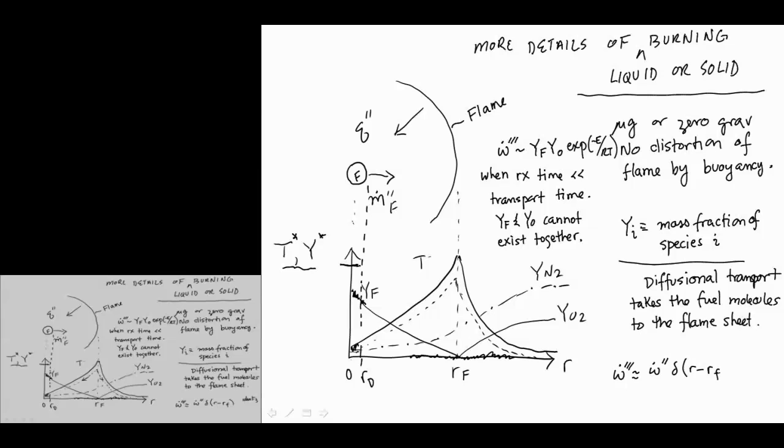And the temperature, because the energy release rate in the energy equation basically looks like W triple prime times the heat of combustion, this also, that source term occurs at the flame sheet, and you get this diffusion process down, and it's that diffusional heating of the droplet that causes a temperature increase, which of course is what is responsible for the high mass fraction of fuel at the interface.